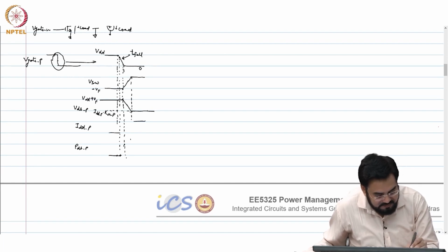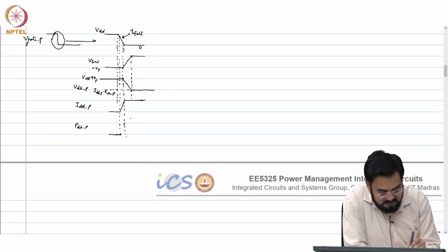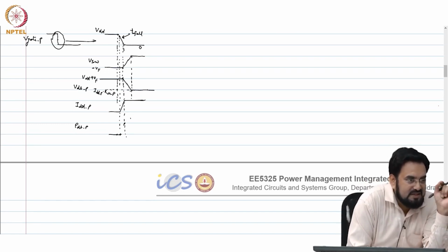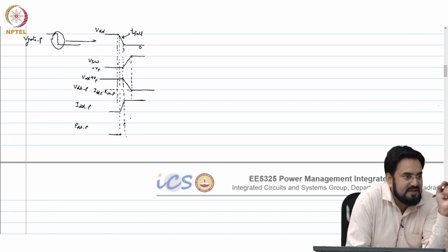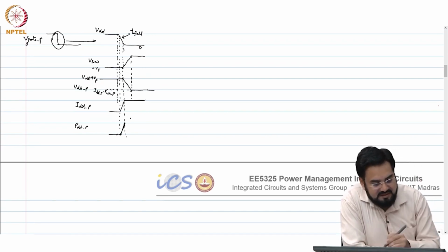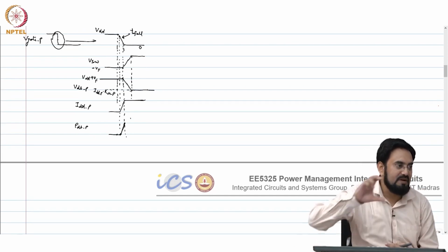So, okay. Now, you have to take the product of the two. So, the point at which you attain the load current, that is where your VDS starts dropping. So, the peak power in the MOSFET will be at that point. So, it will look like a triangle, correct, and then the VDS of your MOSFET starts dropping. So, the power will start again.